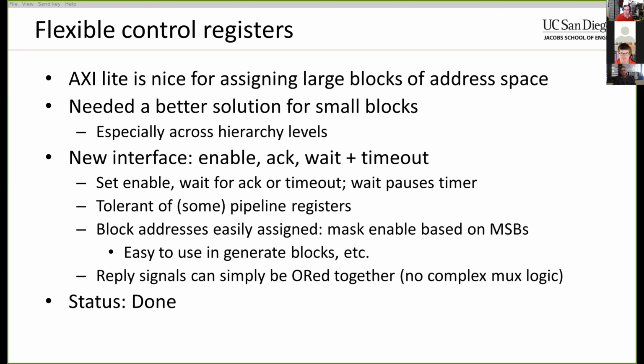I needed a way to assemble register spaces across multiple blocks, potentially even spanning hierarchy levels. So for example, for all of the board-specific code, we have a few control registers for controlling IO pins and interfacing with the optical modules and the board management electronics. That sits at the top level, and then inside of that we want to have the core logic, which actually implements all the control registers.